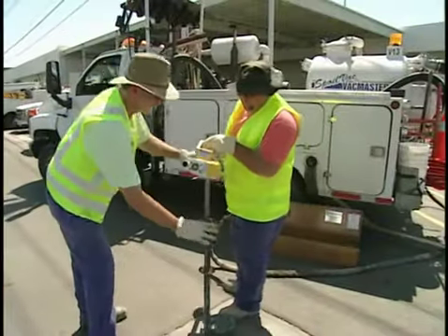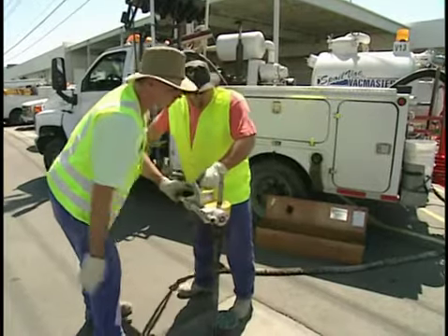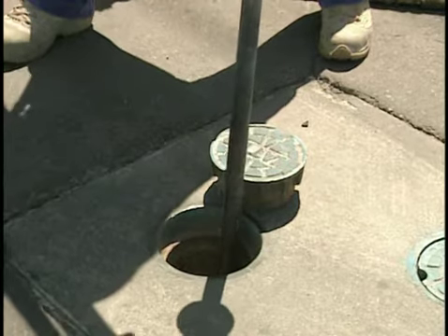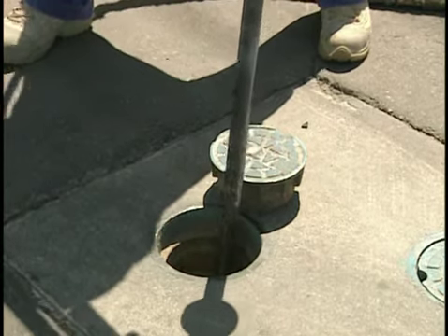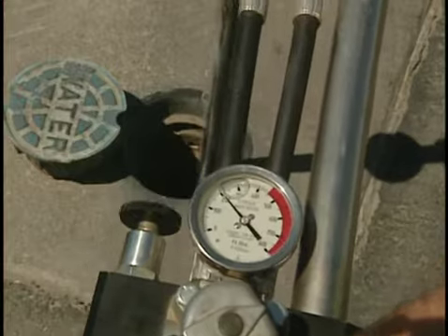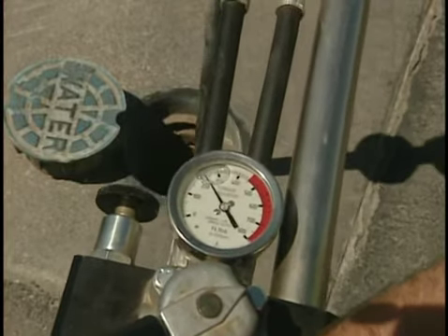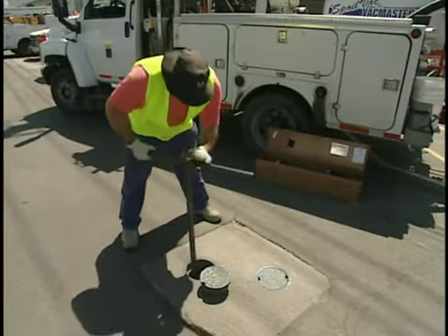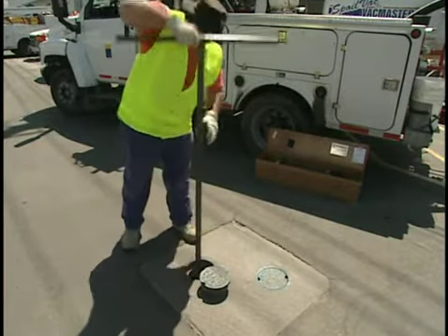There are several types of portable electric and gasoline-powered tools used to operate valves. This will speed the work of exercising valves, but a power operator should have a torque limiting device to make sure excessive pressure is not applied to the valve stem. It's also recommended to manually apply the last few turns of travel in both opening and closing valves.